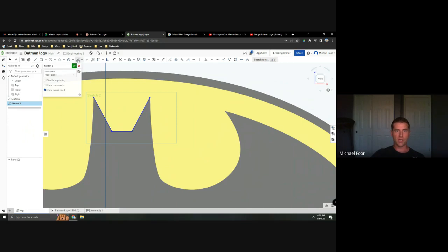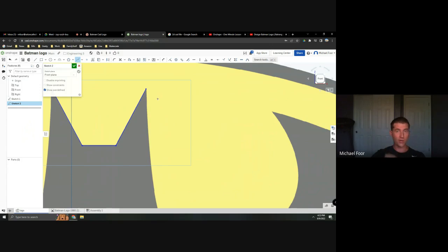Let's choose the spline tool. A spline is a curvy line that makes all of the points that you insert tangential to the line itself. If you're a math person, tangent means that it just curves around instead of being bendy and weird. So we'll grab our spline tool and I'm going to start from this point. I could click wherever, but you want to be careful because remember, in order to make this a full, closed path, it needs to be a closed shape, which means that we need to start our spline right here at this point.